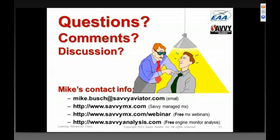Okay, John is wondering, is there a difference in monitoring CHT when using spark plug temperature probes versus cylinder well probes? Yes, there is. And I generally recommend against using spark plug gasket probes, but if you have to use them, the spark plug gasket probes normally give you a CHT reading that's about 40 degrees Fahrenheit higher than what you would get with the standard probe that screws into the well. So if you are using spark plug gasket probes, and that's a good question, you need to increase all of those CHT targets by about 40 degrees. I recommend not using those gasket probes unless you have to.